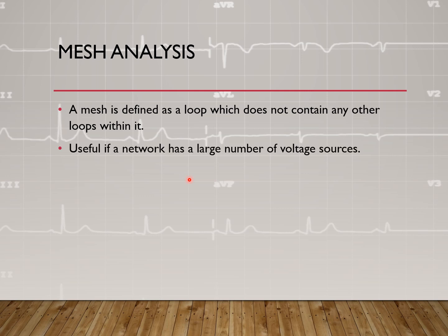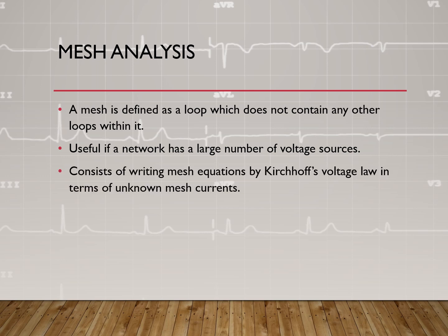It is useful if the network has a large number of voltage sources. Normally in mesh analysis, we write KVL. KVL is what is used for mesh analysis: Kirchhoff's voltage law in terms of unknown mesh currents. We write the voltage expressions in terms of the unknown mesh currents which are decided.